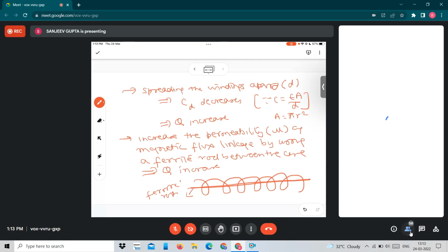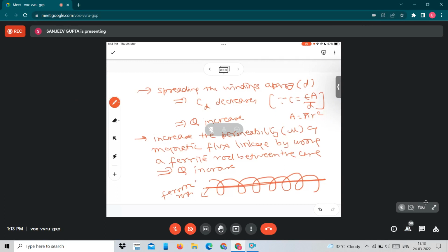Like in the case of R, L and C will be the parasitics. In case of L, C and R are the parasitics. And in case of the capacitor, L and R are parasitics. So the parasitic elements are always there. So we always speak in terms of impedance, never these values. Another thing which you have learned is that measuring using a DC multimeter will not help, because we have to do the calculations for the various parameters or specifications to get the best inductor or best capacitor and so on.